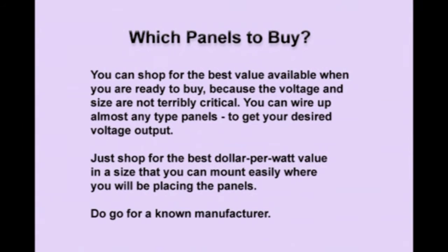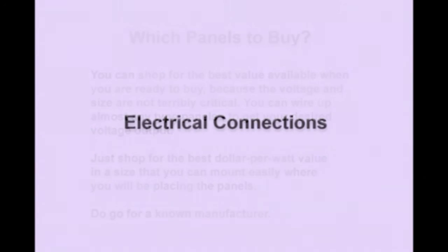So what type of panels should you get for a particular job? You can go and shop for the best value available when you're ready to buy, because the voltage and size are not terribly critical. We can wire up almost any type of panels to get your desired voltage output. Just go and shop for the best dollar per watt value in a physical size that you can easily mount where you will be placing the panels, and I would suggest you do go for a known manufacturer.